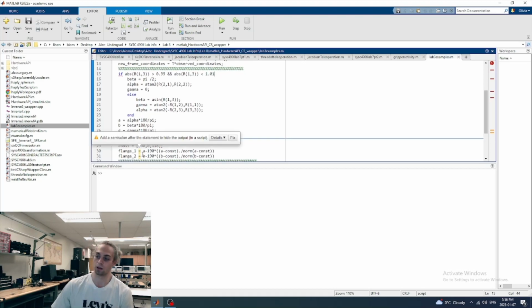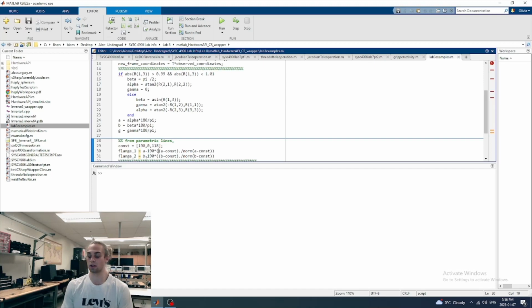So what you would do is you would take the point on the base reference frame, and then you would move backwards. So I'm subtracting 190. You'd move backwards by the t value, which is a scalar 190 millimeters, times the unit vector made from the point on the base reference frame to the constraint that's been given. And you'll do this separately for each point because the flange will actually have to change location when it points to a different stone.